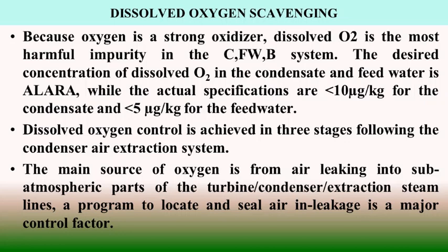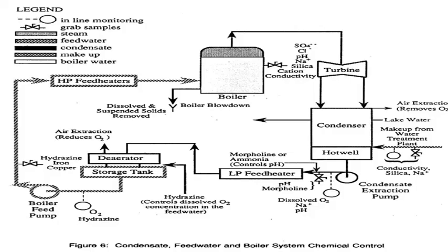This efficient stripping action reduces the consumption of hydrazine also. So the deaerator improves the effectiveness of the oxygen scavenging and reduces the consumption of hydrazine.